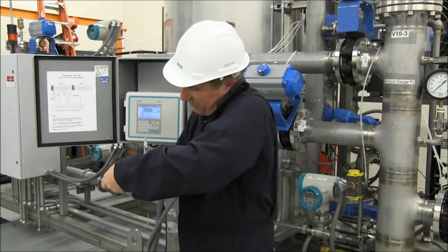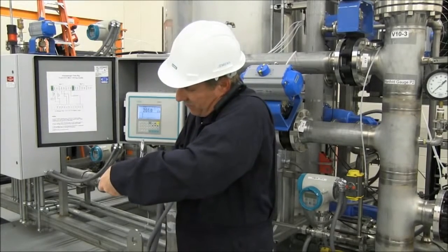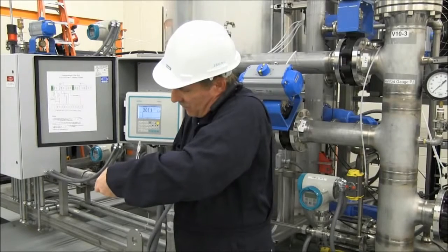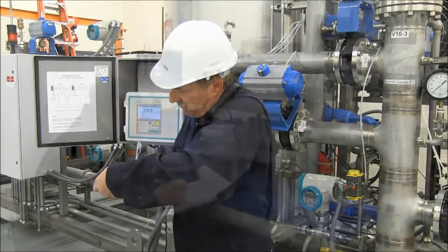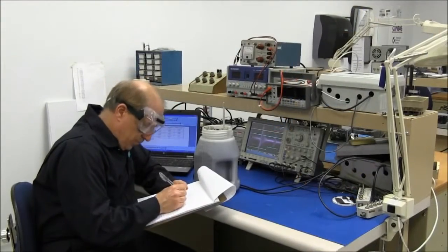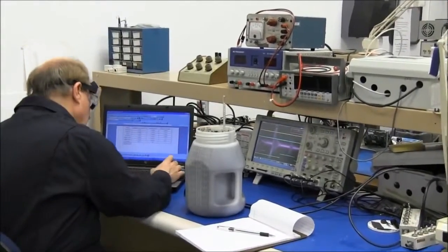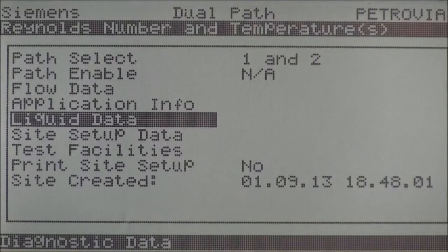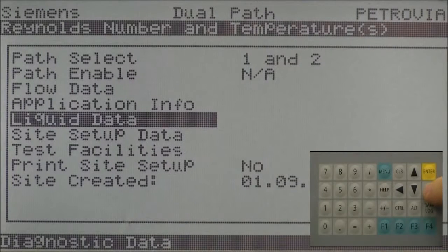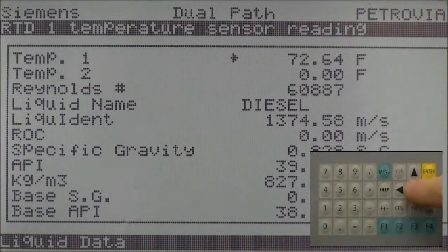Timestamped samples can also be collected for a longer time frame, for example 1 week, and compared to data collected from the FUH1010 data logger. The procedure is the same either way. If a liquid sample is taken, density and viscosity must be determined with the use of laboratory equipment. The values must be for your liquid at base temperature. Then compare these reference values to the values indicated by the FUH1010, which can be found in the liquid data section of the diagnostic menu.